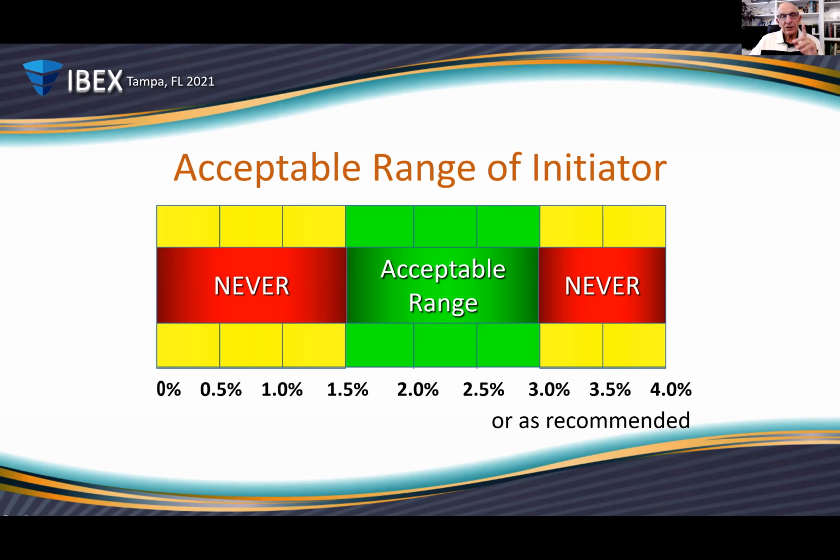I also might mention that if you happen to be one who uses the summer catalyst, the 5% active oxygen, you are at great peril of permanently undercuring your gel coat. Yeah, it'll get hard. Yeah, you'll get the part out of the mold, but the cure won't be thorough. Those summer blend initiators have less active oxygen in them.